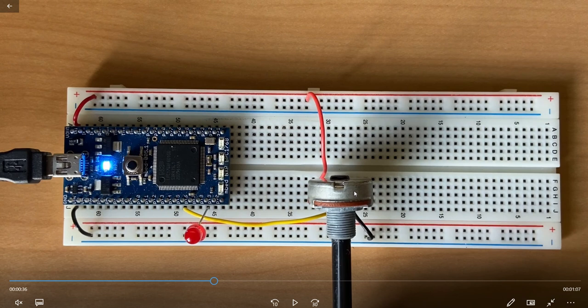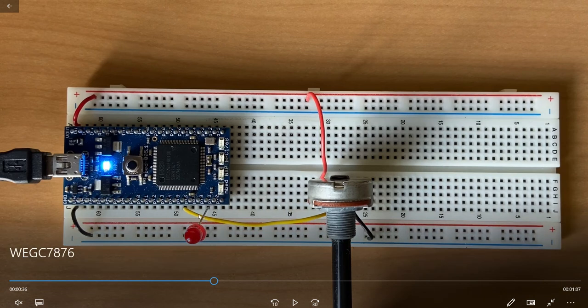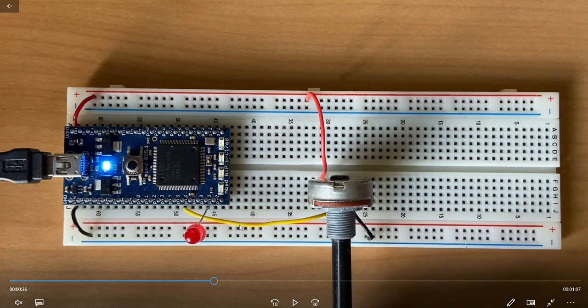So as we change the resistance, it's going to change the voltage that's going in on pin 15 at the moment, which is one of our analog input pins. So we know our analog inputs are pin 15 down to pin 20. There's 5 of them. So it's giving us a varying voltage, which is ultimately an analog input because it's just changing. It's not just an on-off signal.